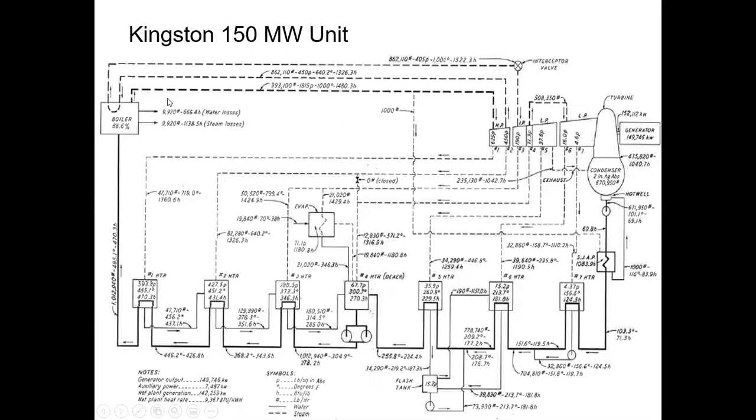Let's see, this is the main steam line. It's almost 1,000,000 pounds an hour. Pressure, the absolute 1815, so 15 for atmosphere, 1800 psig, 1,000 degrees Fahrenheit. And they even give you the enthalpy on the diagram. This is BTUs per pound, 1480.3 BTUs per pound.